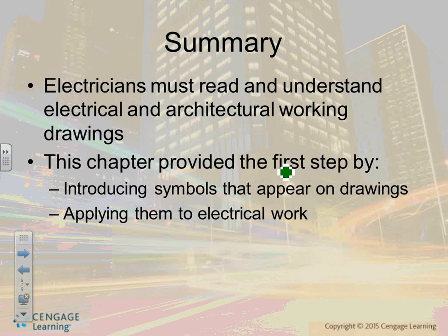On page 43, my friends, we have motorized and HVAC equipment symbols, and next to them the distribution equipment. I want to focus on this panel, guys, right here. Lighting or panel power on a normal generator set feeder. That's how they do it. If you have a distribution panel on normal or generator feeder, this is how it looks. If you see them different in our project, don't sweat it too hard.